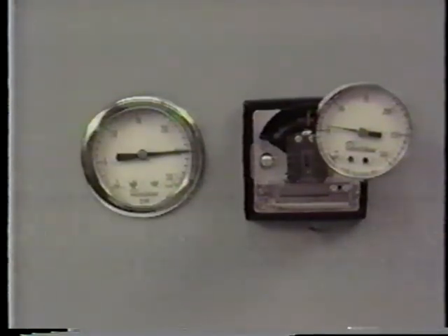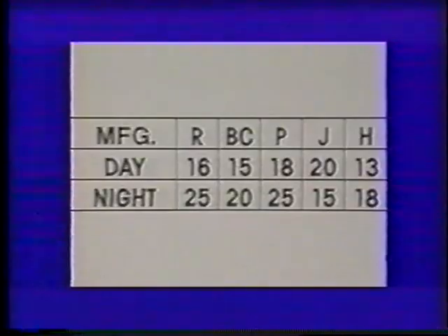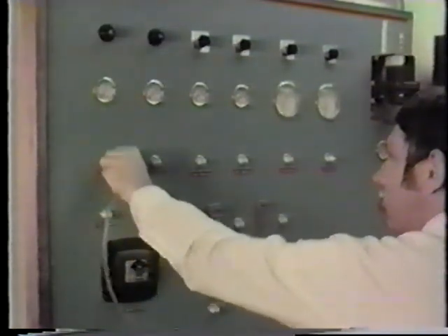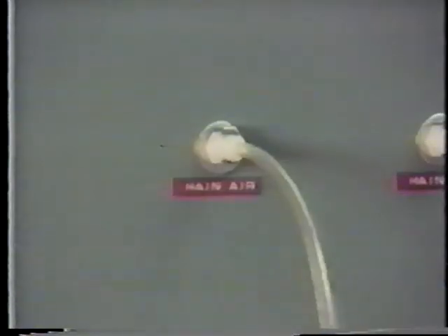The Robert Shaw day-night thermostats are factory calibrated to switch from day to night operation between 17 and 21 psig main air. This setting matches existing Robert Shaw systems, so no switching adjustment should be necessary. If this device is to be used on a competitive dual pressure system, it may be necessary to make a switching adjustment. The switchover adjustment should be done on a test bench where a variable main air supply is available.